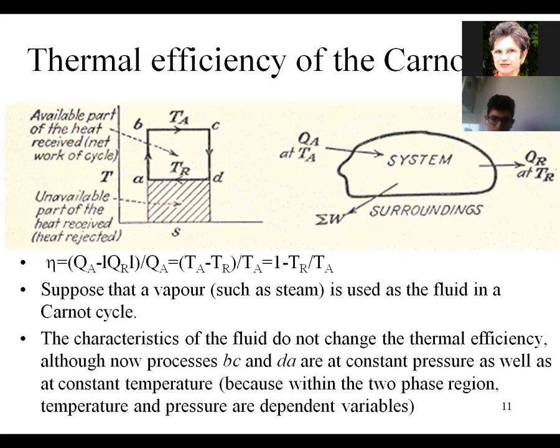As you know, from the second law of thermodynamics, it is impossible for a cycle to run as a motor cycle if it is not in connection with at least two reservoirs. So from the surrounding, the system receives at TA, high temperature, energy input in form of heat. The cold reservoir receives from the system another part of heat that cannot be used by the system, unfortunately. And in the meantime, the system is doing some work for the surroundings. Here is the expression of the thermal efficiency.